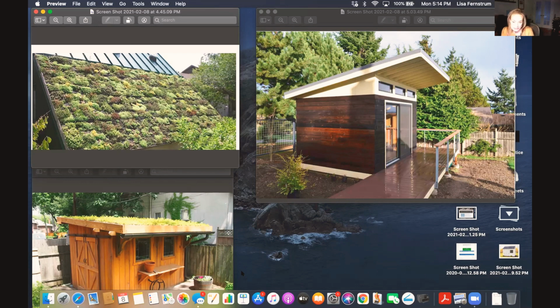Some of the cons are connected with that draining of water at a 6-degree angle. There is a need for boxed gutters. The gutters actually need to be doubled to catch all that water coming down in one direction. Another con is that a lot of people don't find it as aesthetically appealing as a regular roof. And like Lisa said, you can't use it for larger homes.